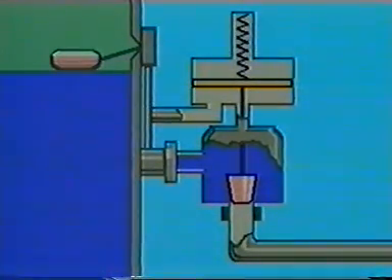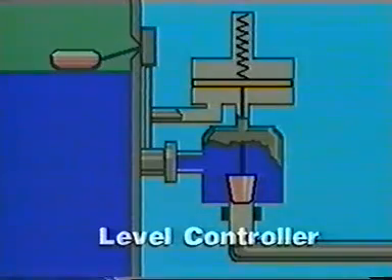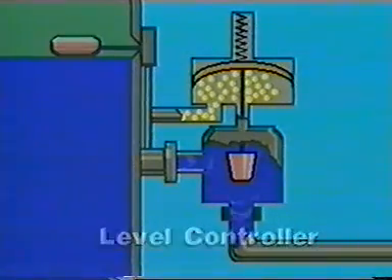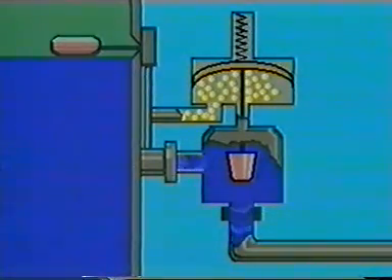Glycol level control on the contactor is important in stabilizing unit operation. The level controller should be adjusted to hold a uniform flow rate of glycol out of the contactor. It is more important to hold a constant flow of glycol out and let the glycol level in the contactor vary a few inches, than to hold a constant level in the contactor and let the flow out fluctuate. Flow rate surges leaving the contactor will cause the reboiler to operate inefficiently and may overload it.